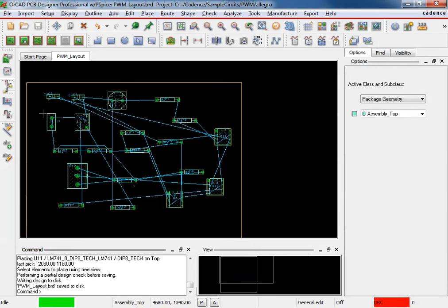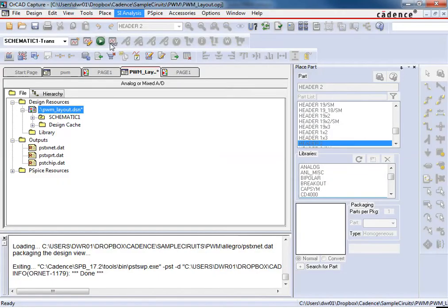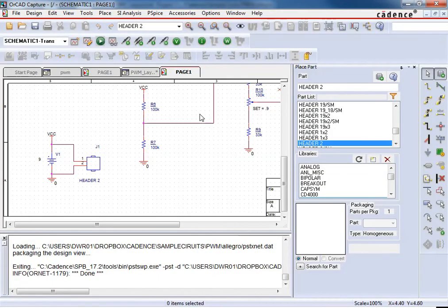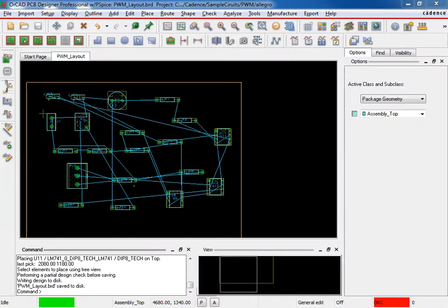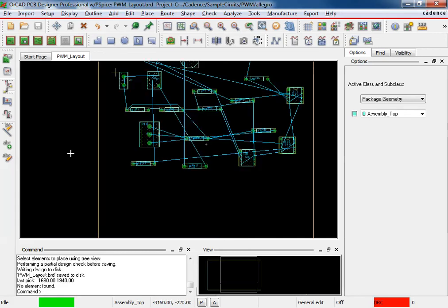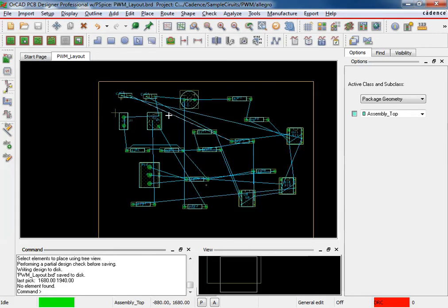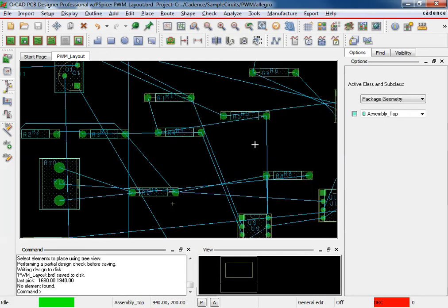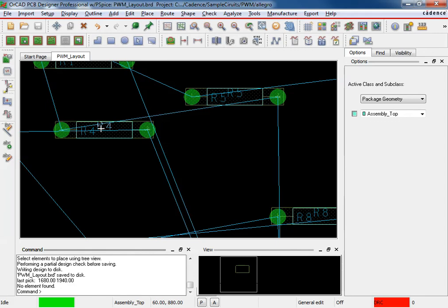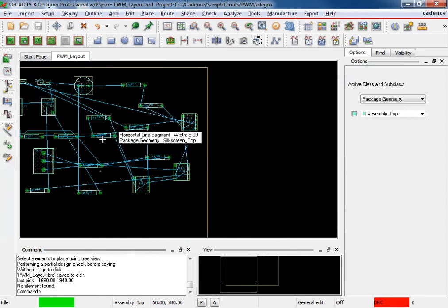For some reason this program likes to crash. Now the one thing I'm going to do here is open up my circuit diagram. I'm actually going to move it into my other window here because the next step is what's called de-rat nesting. Now this is what's called a rat's nest. Blue wires are showing where all the connections need to be made. Now if I zoom in, you can see R5. You can see that it's got these little designations for these components.